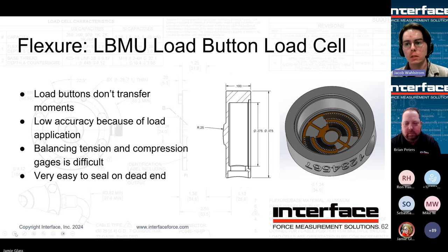And that makes these load cells very, very sensitive to gauge placement. So you can see some rough dimensions here. This is a really small load cell, right? It's, I think, smaller than a quarter, maybe smaller than a penny. You can think about trying to install 4 separate gauges in very specific spots repeatedly. That's going to be really hard to manufacture, and really hard to have good, consistent performance.